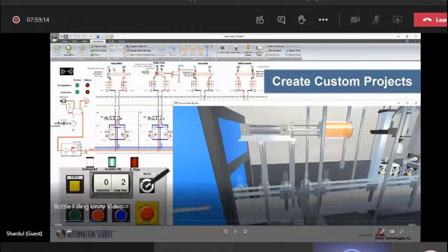On the left, you have different pneumatic cylinders created here with different sensors mounted, and the pneumatic source, that is the compressor driven with a shaft, is here. You have the accumulator as well, and then you have the FRL, the regulator unit. After that, the pressure from the pneumatic source goes through different cylinders. This is my meter-in and meter-out circuit with meter-in meter-out orifices. And then if you observe properly, under that you will see that you have a conveyor line.